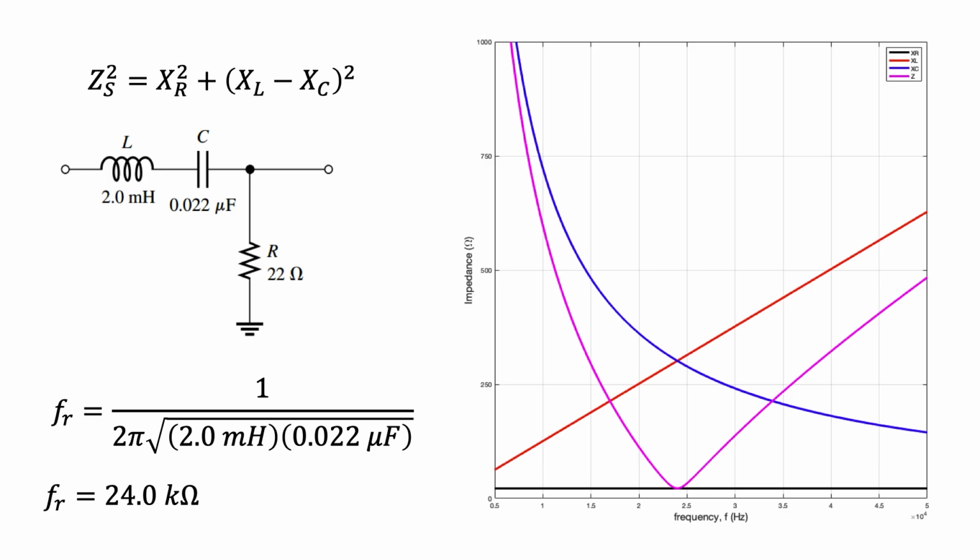As the frequency is slowly increased, XC still has a very large value, but XL also has a value, even if it's small. The total impedance then decreases not only because XC decreases, but also because of the difference XL minus XC. This means that the current can flow through the circuit elements, slowly increases with frequency, and the voltage is also present across the circuit elements. It follows that VC is greater than VL at these frequencies.